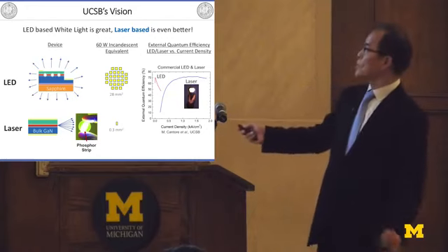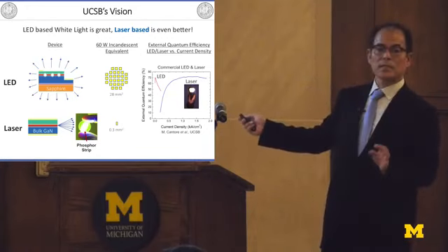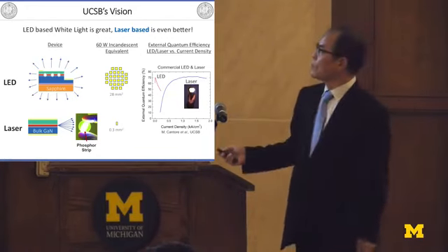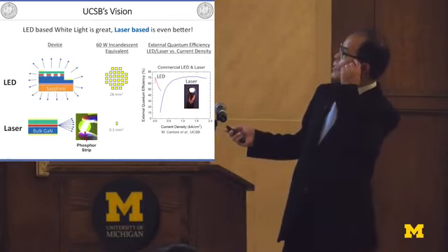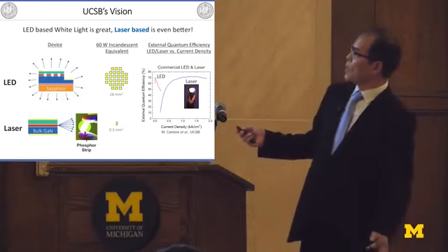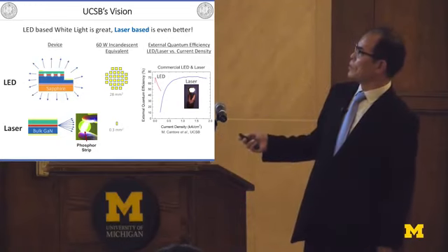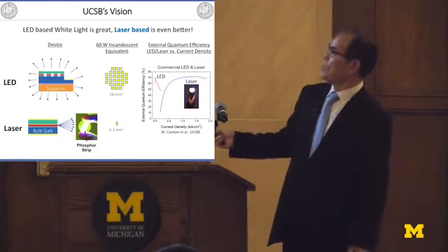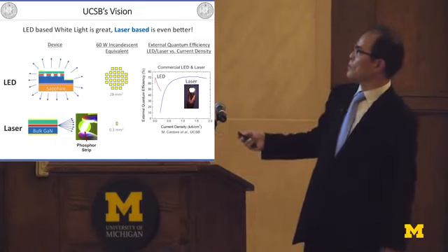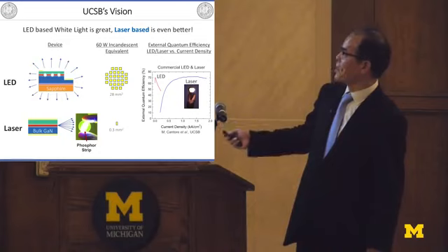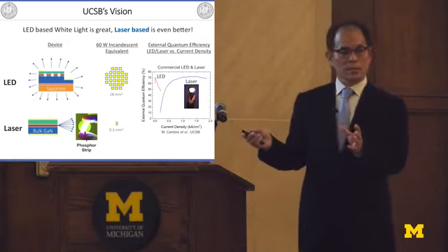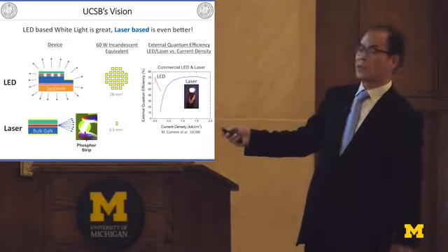So current density more than 1,000 times higher than LED, still efficiency very high. For example, when we make a 60 watt incandescent equivalent lamp, in the case of LED, the emitting area should be this size, because the current density always should be around here, almost zero current density. So in order to reduce the current density, emitting area should be very large.